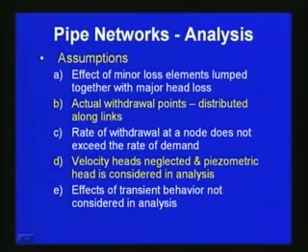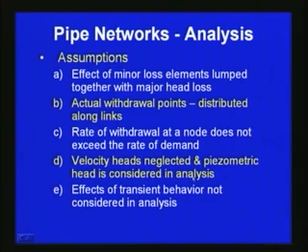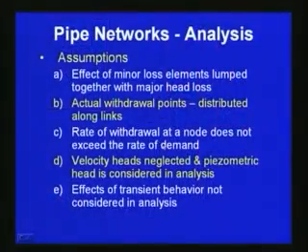And then the fourth one is that velocity heads are generally neglected, since the system is so complex that if you consider all the things it will be very difficult to solve. So, velocity heads are neglected and the piezometric head is generally considered in analysis. As we have seen in the system earlier, we will be considering the piezometric head, and the velocity head is neglected. And the effect of transient behavior is not generally considered in this kind of analysis, since the analysis is so complex. So, we may not consider the transient effects. Based upon these assumptions, we try to solve these kinds of complex pipe networks.